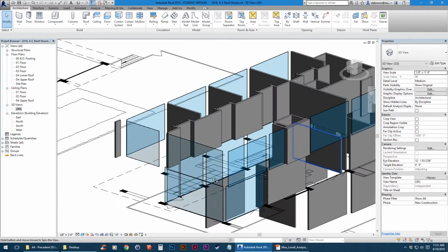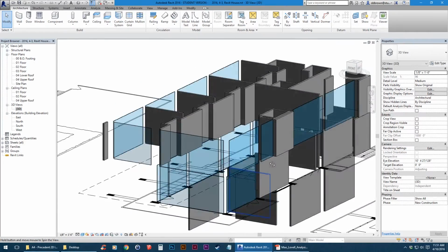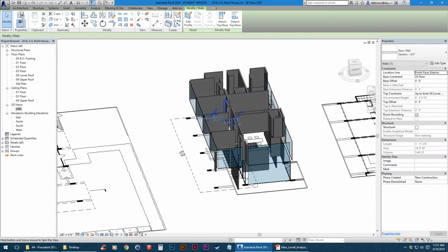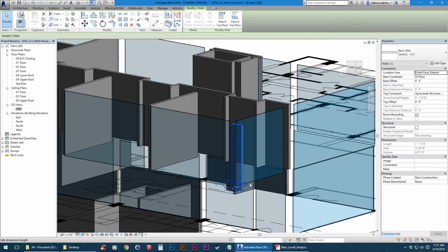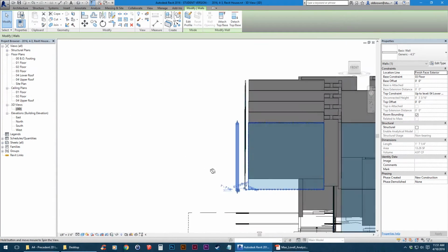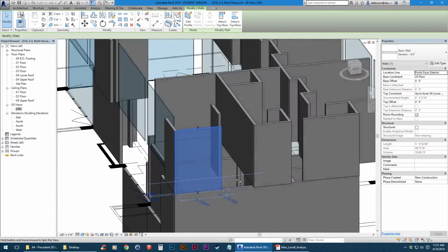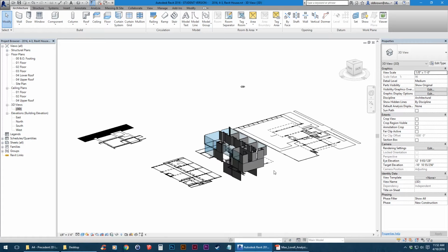If you're rotating around, you can do that if you hold shift and then click on your scroll wheel. Like right now it's hard to tell where the mouse is centering around. So if you click on an object and then start rotating, that's where the view will rotate around. So it can be helpful if, say, you want to look around in this area, you can highlight this object, and then your view will rotate just around there. So you can jump around to something on the opposite side, then move around there. And another shortcut, say you want to zoom to this whole view, you can type in Z and then A, and that'll zoom all. So it basically zooms everything in that view.